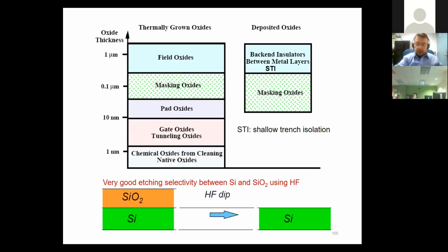Okay, so based on the type, the different oxides can be listed with respect to their thicknesses too. The field oxides were mainly for insulation, right? So their thickness is at an "I don't care" level. They are very thick. As we go to the more precious items like the gate oxide, one of the main building portions of the transistor, their thicknesses are of course much thinner, and the quality has to be super good.